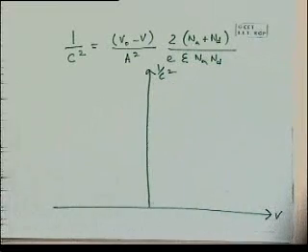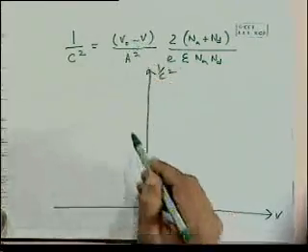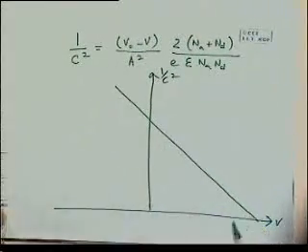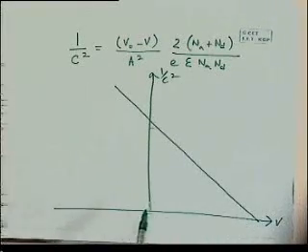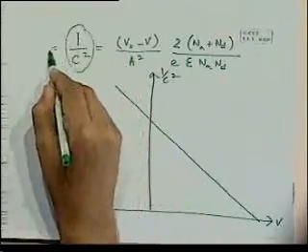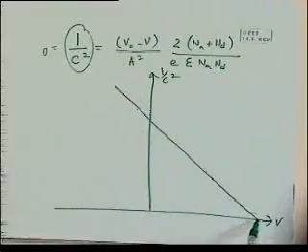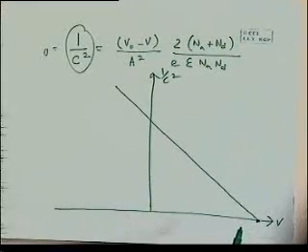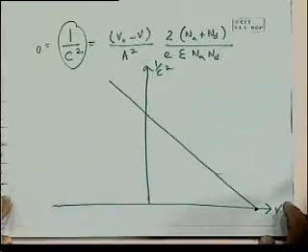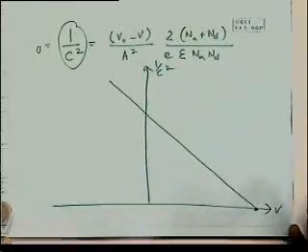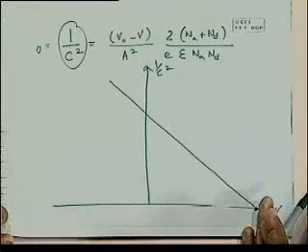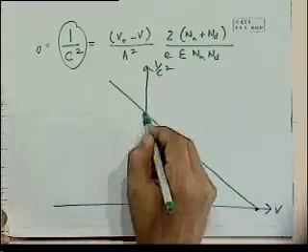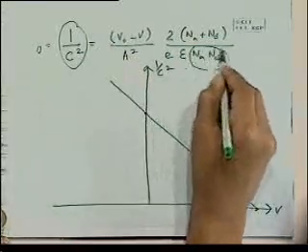What could we expect? A straight line with a negative slope, right? So we would see something like this. And when the capacitance, or this 1 by C squared term, is equal to 0, which is at this point here, what is this value of V? V naught, right? So by measuring the capacitance as a function of voltage and then plotting it as 1 by C squared versus V, the x-intercept where it cuts the x-axis is my built-in potential. And related to the y-intercept and the slope come these parameters, N_A and N_D.